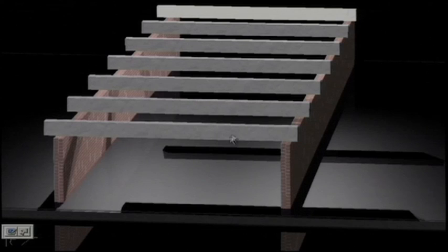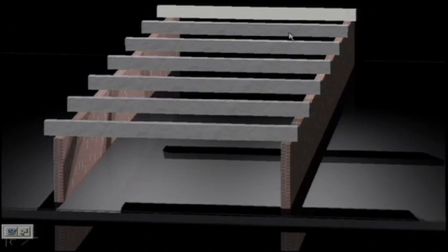What we can do, you can take the end beam and the other end beam, those two end beams you can design separately, because they will have less load compared to the inner, intermediate beams. The intermediate ones will have more load because you are getting slab load from both sides, the dead load of the slab as well as the live load.